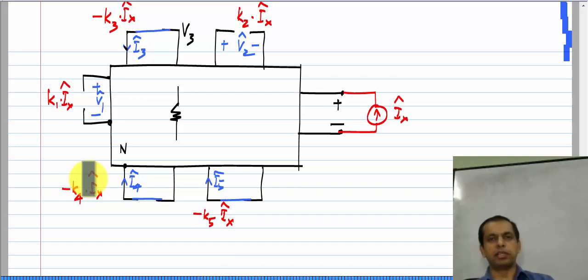Now, in this case it turns out that it is particularly simple to turn the whole picture around and apply an excitation at the output and find what appears in place of each of the resistors. Okay. So, that gives you the transfer function, which is also the same as the transfer function from the resistors to the output. Okay. And by using this reciprocity, the simulator is able to calculate the noise transfer functions very easily. Okay. So, that is the application of it.